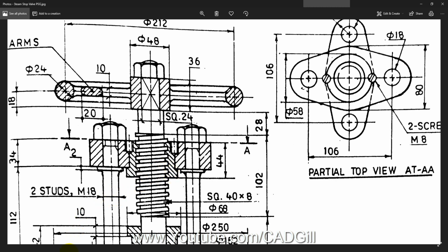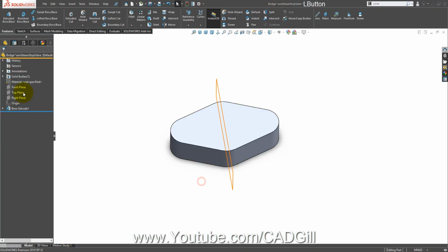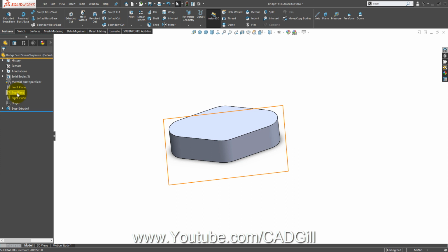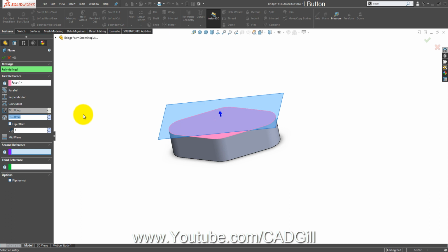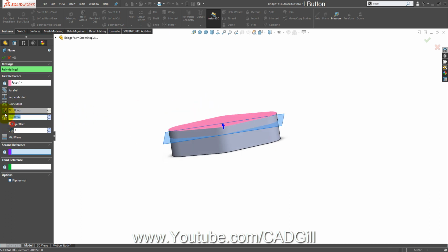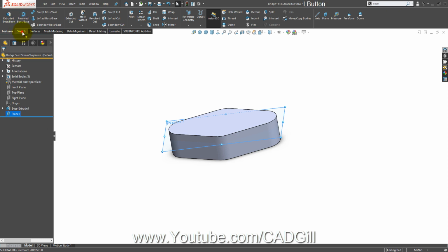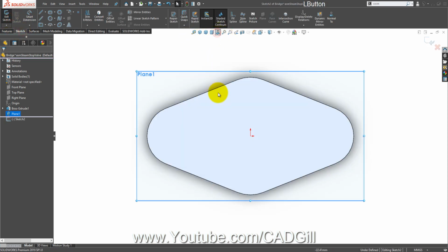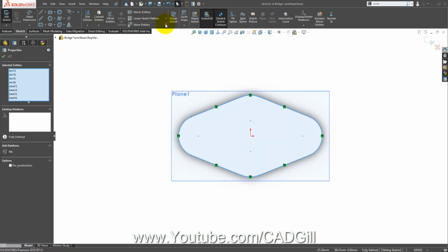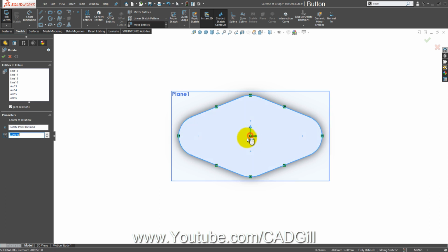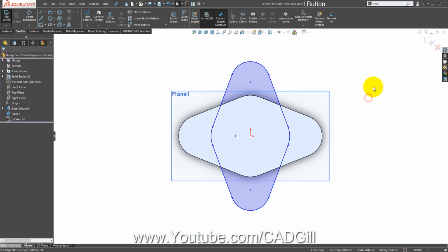Let me just make this here. I will select this plane, and reference geometry, 10, flip direction. Then let's select the sketch. I can just select this sketch, convert it, and rotate it about this point at 90 degrees and uncheck keep relation, click OK. This was pretty easy.